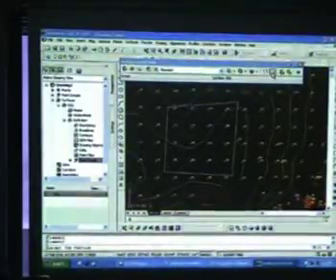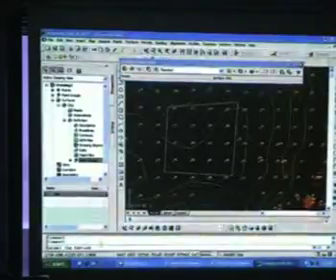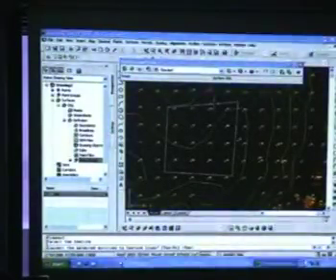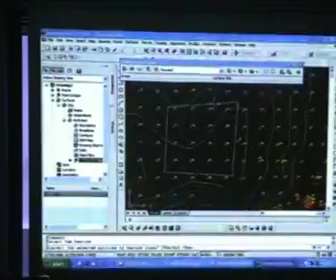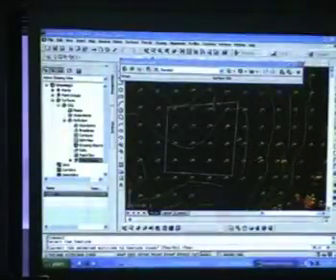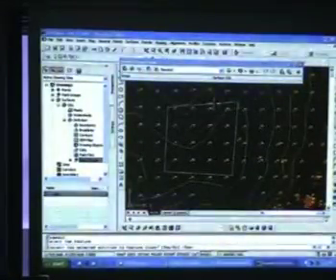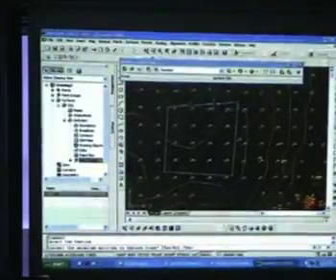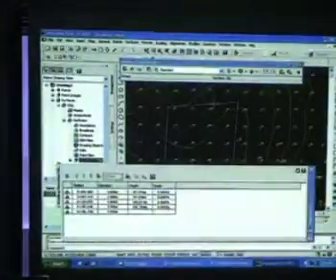And then it'll ask you to select the feature. So just select the white line. And then it'll ask you to convert the selected entities to feature lines. This is because for grading, you need to use feature lines instead of normal polylines. So what it does is it will convert this for you, and you just say yes.